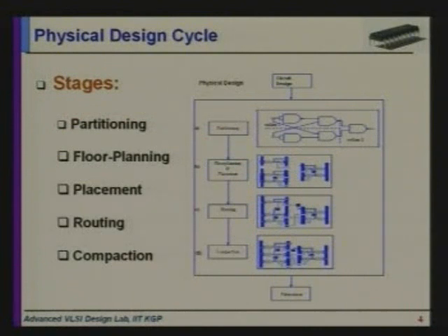Partitioning: we partition it. You see part A of this figure. It divides this circuit into 3 partitions, and then individually tackles the problem of generating the layout of each of these 3 partitions and the interconnections between these partitions.